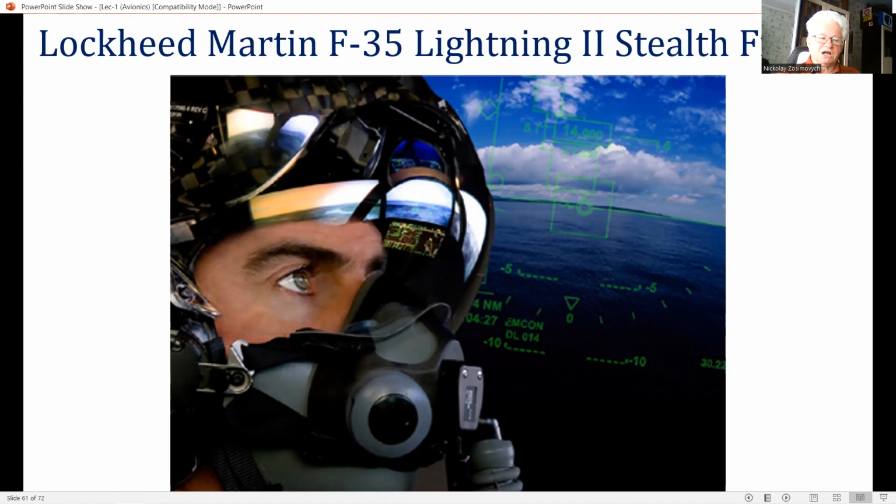Miniature night vision cameras are mounted on each side of the helmet, and the binocular video image is displayed on the HMD. The infrared video image seen from the gimbal infrared sensor can also be displayed on the HMD to provide a complementary night vision system.